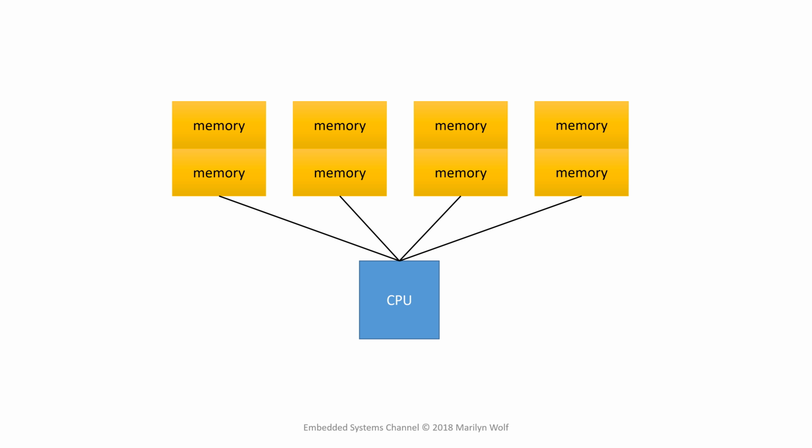Many memory systems consist of not one memory array but multiple memory arrays. So we can organize a given block of memory into banks. Each bank is a two-dimensional array that provides one form of parallelism. But we can also have multiple banks spread across different channels. The CPU provides multiple channels that can operate in parallel, and this provides a separate form of parallelism in the memory system. Taking advantage of that parallelism is an important part of software design for embedded computing systems.